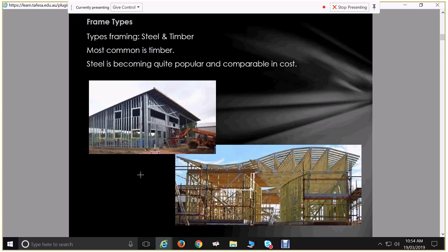We get heat from the sun on our steel sheet roof. That goes to steel purlins, which are attached to steel rafters, which, if we've got a flat ceiling, are attached to our ceiling. That heat is transmitted directly through all of those members. If that's a piece of timber, and the steel sheeting gets hot, our batten gets a little bit hot, our rafter doesn't really get very hot, and then our ceiling, we're not transferring it. So they're the main differences between them.